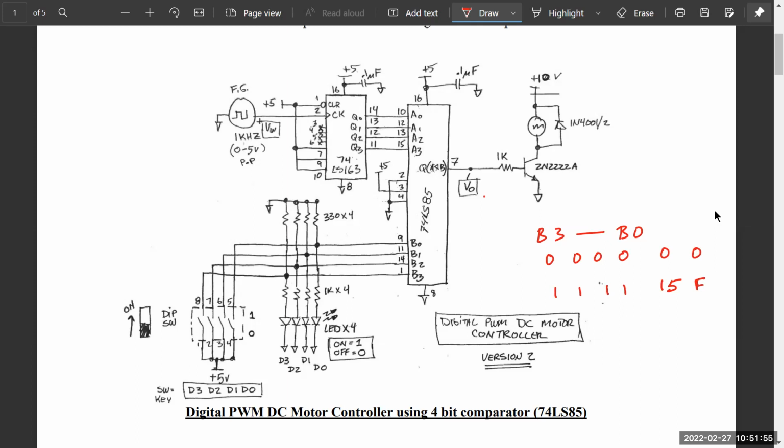What we are doing is, well, we're taking the input pins B3 to B0, and we connect them to ground. If you look at this pin configuration right here, these are all connected to ground. Now, of course, we have a resistor in there to limit the current and also to prevent a short circuit between our plus 5 volts and ground.